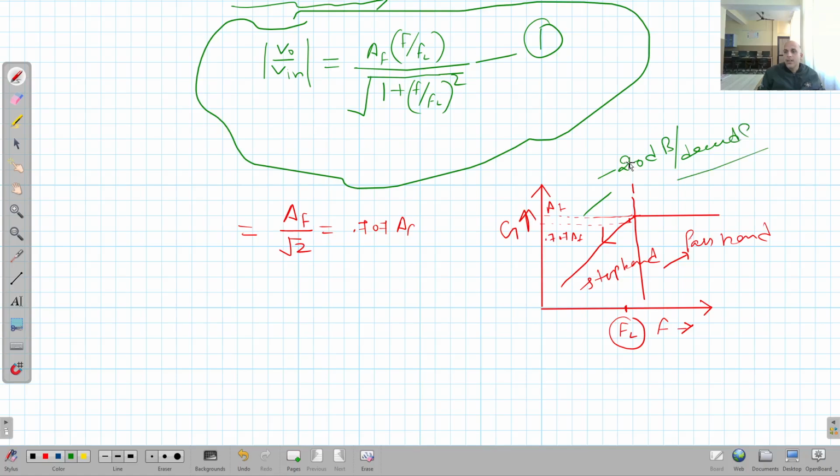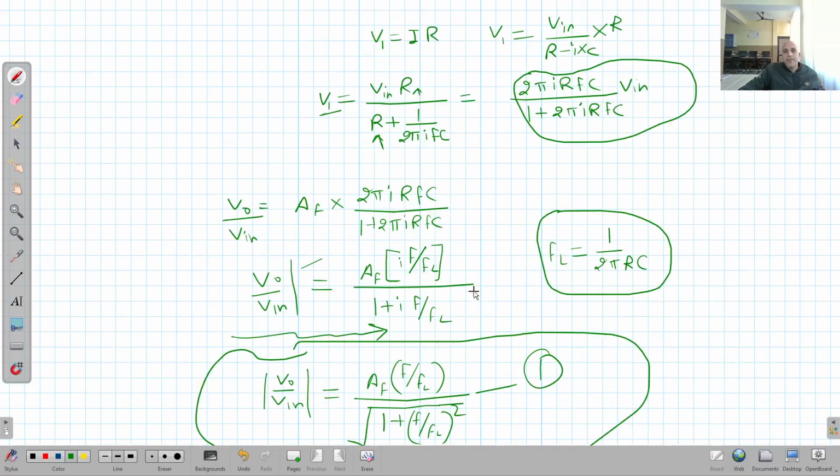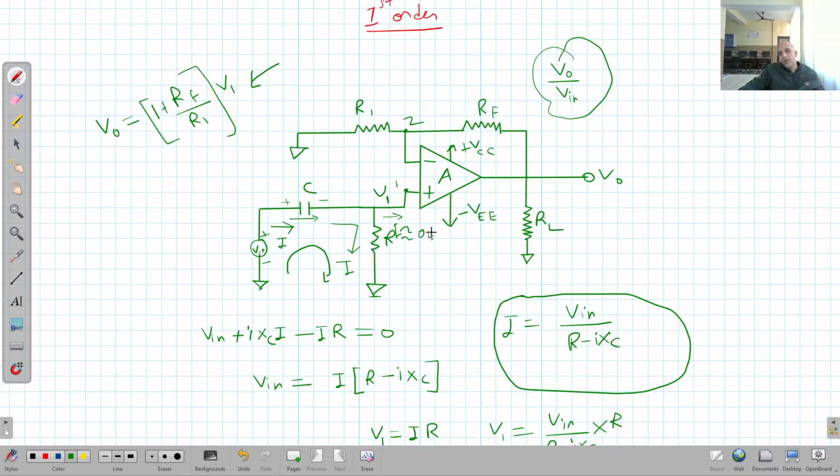So again the same thing that was in the case of low pass filters. The roll off rate is same. In case of first order low pass filter, it is minus 20 decibel per decade. Clear? We will see that in the case of second order it will become double, right? So this is about the Butterworth high pass filter of first order.